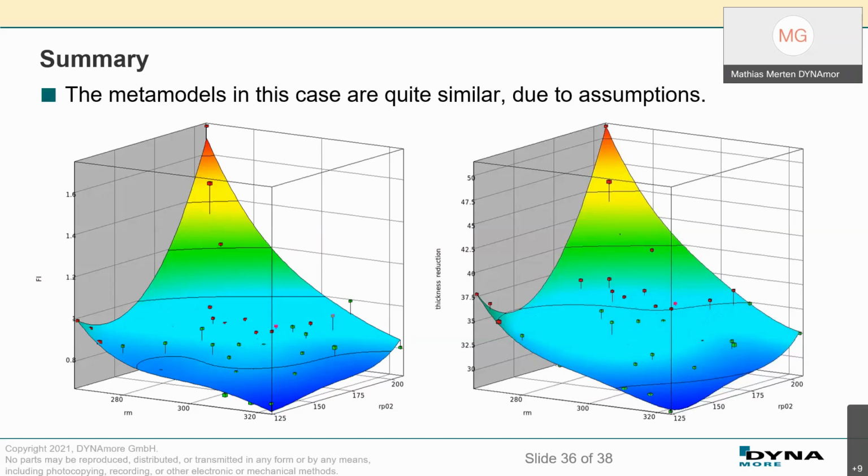So finally, this is also a function of the in-plane straining. Both responses we have chosen here describe the strain state, and you can expect that the maximum value of the thinning is connected to the maximum forming of your sheet. Therefore, it could have been expected that both look the same.